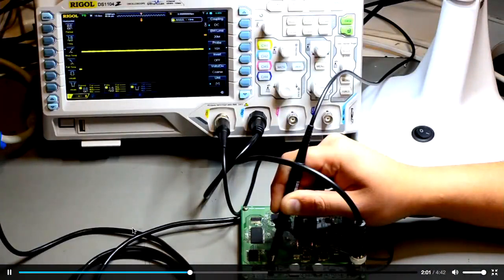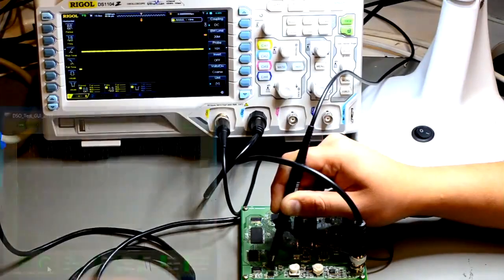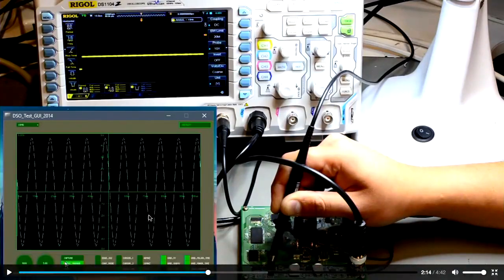The next thing we're going to be going through is the trigger circuit. The first thing you're going to want to check on this is the output voltage of the DAC. In the GUI, when you change the trigger level, you should see the voltage from the DAC increasing and decreasing. This is the interfacing GUI we will be giving you; you don't have to program or make it.